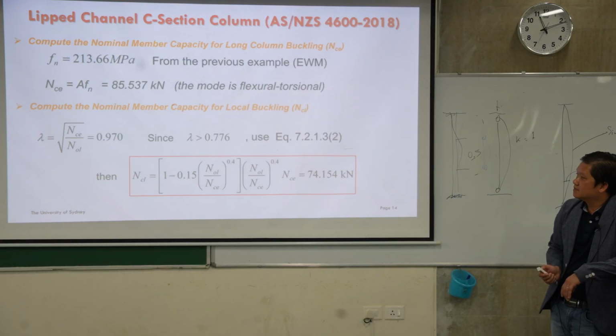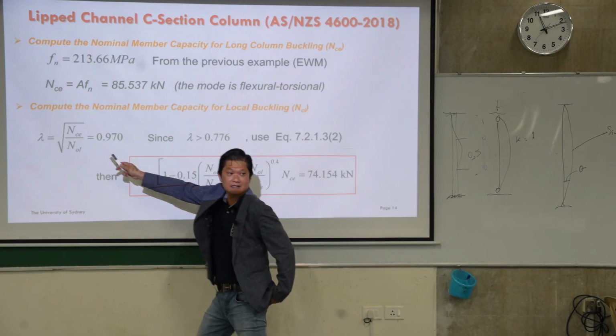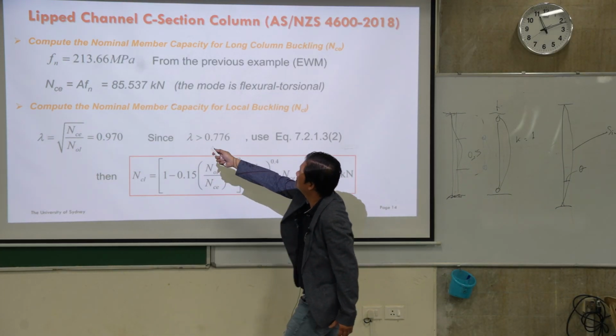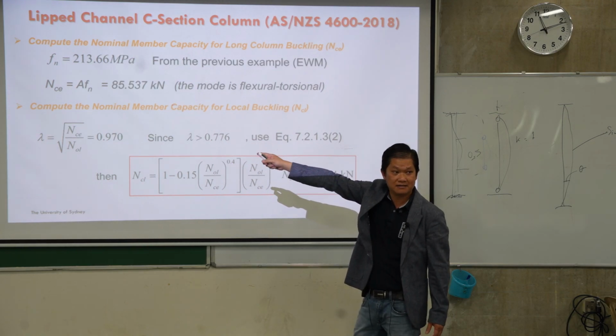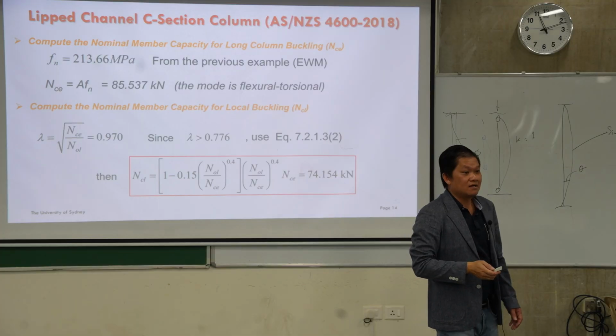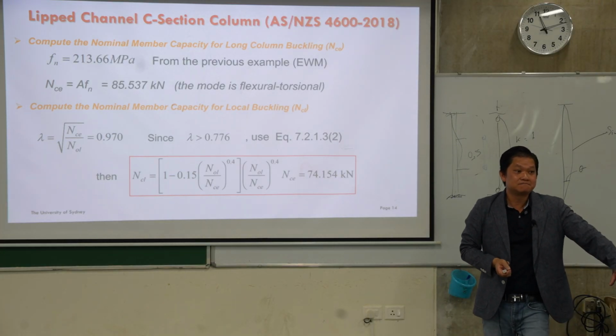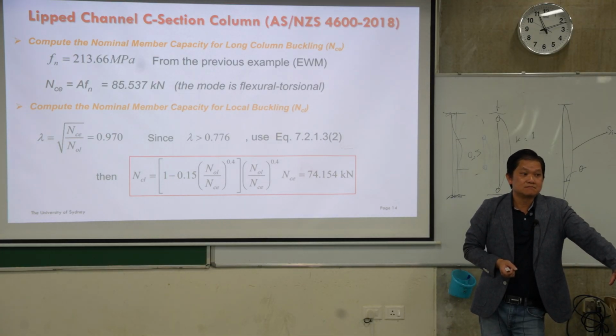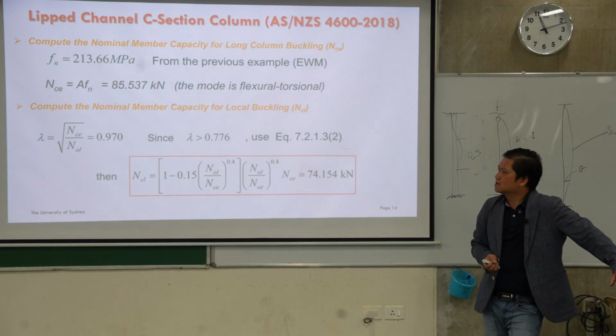Yeah, that Fcr is your calculated global buckling stress. Here, we are actually getting the global buckling stress also. Can we directly take that as critical buckling stress? From that, we can calculate the critical buckling load and substitute in the equation.